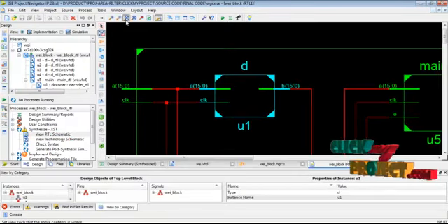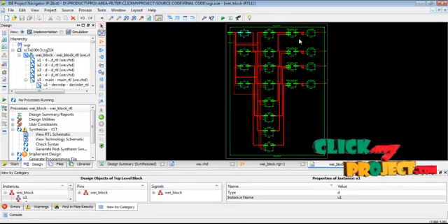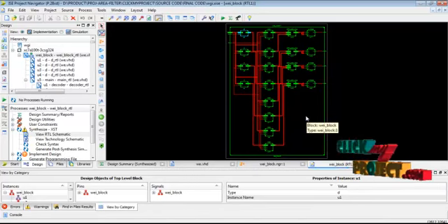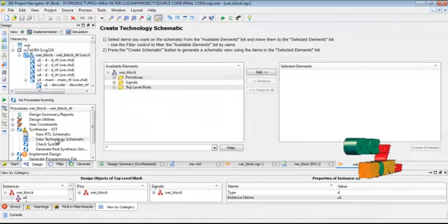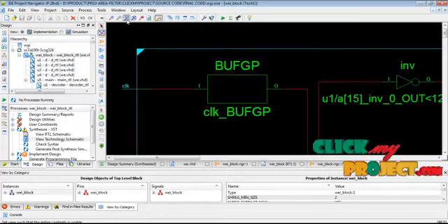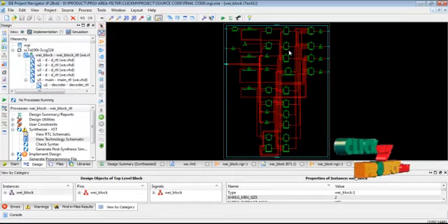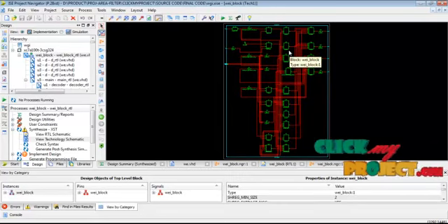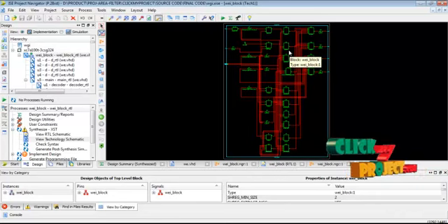We double click this diagrammatic representation, which shows what logical blocks are placed in our weighted filter architecture. Then the technology diagram represents the lookup tables, input output buffers, wire connections and flip-flop pairs applied by our overall weighted filter architecture.